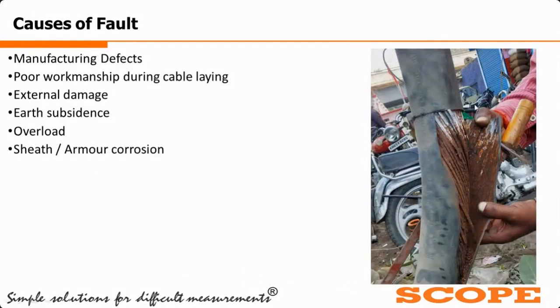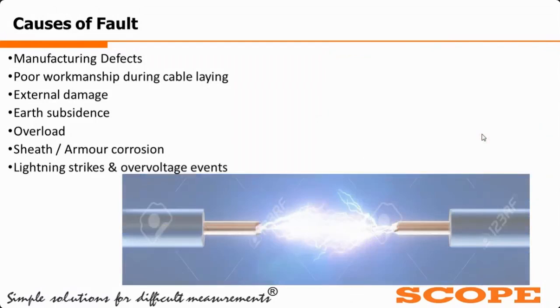If the insulation of the cable got damaged from the outer layer of the PVC jacket, moisture enters the cable, and due to the entry of moisture, the armor of the cable gets damaged and corroded. Due to this corrosion, the insulation inside the cable is weakened after a particular period of time, and faults occur in the cable.